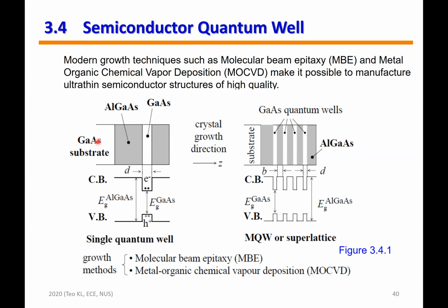Usually, we will grow the material on a semiconductor substrate. The gallium arsenide substrate usually manufactured by the vendor is mechanically polished, and often this substrate can be semi-insulating, N-type or P-type.